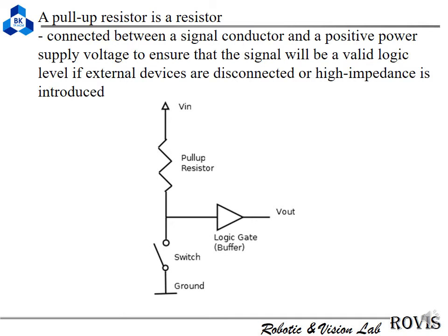And the next one, we have another definition. This is the pull-up resistor. Okay, why do we have this one? As I discussed before, in a microcontroller we use a digital system. We just have low and high values, right? Low means 0 volt, and high is 5 volt.